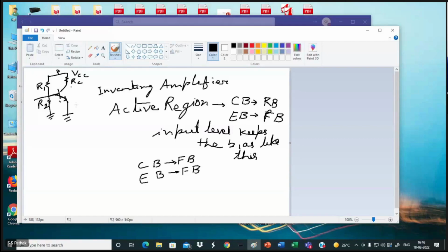Okay, so here this potential becomes larger than this potential. When it becomes like that, its voltage exceeds this potential, and the collector base junction also becomes forward biased. So at that particular input, the switch will be in the on state.